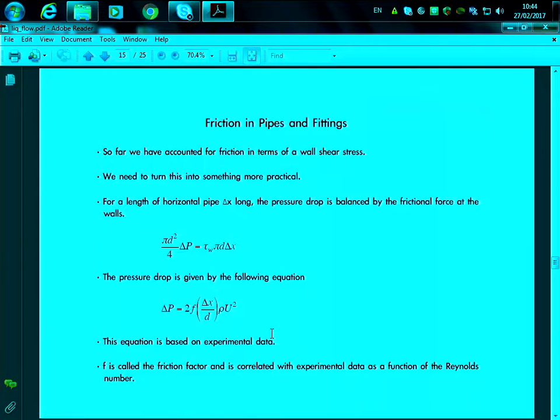On page 10 of the handout, here we have the friction factor using the Darcy equation and the Fanning friction factor. In some books they don't tell you whether it's Fanning or Darcy, they just say F, which is sometimes confusing because these 2 change depending on which one the F is obtained from.